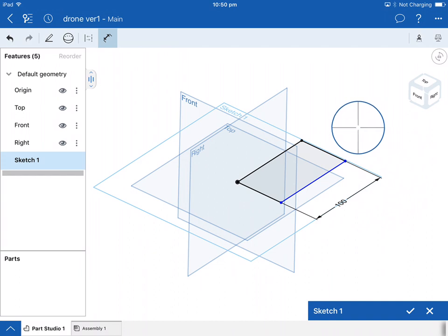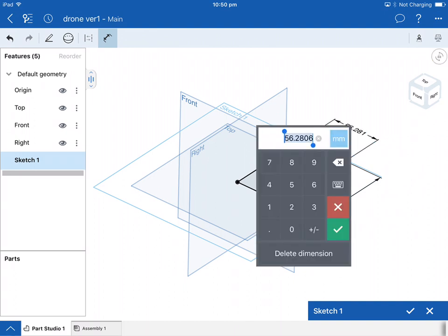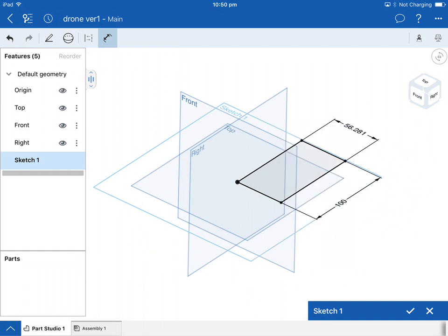So the dimension tool is still engaged up there. I'm going to click on this line, drag the measurement out. Now nothing will happen unless I touch somewhere in the white space. If I touch in the white space, you'll notice this dialog box comes up. Now remember I said I wanted 80, so 40 is half, not 4.